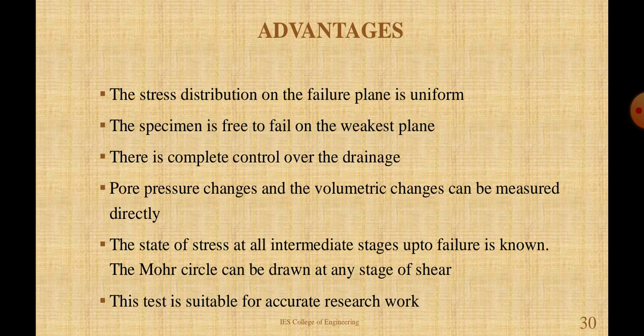Then the advantages of the triaxial shear test. The stress distribution on the failure plane is uniform. The specimen is free to fail on the weakest plane. There is complete control over the drainage. Pore pressure changes and the volumetric changes can be measured directly. The state of stress at all intermediate stages up to failure is known. The Mohr circle can be drawn at any stage of shear. This test is suitable for accurate research work.